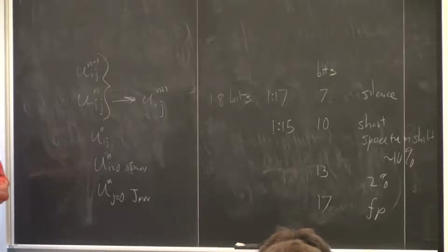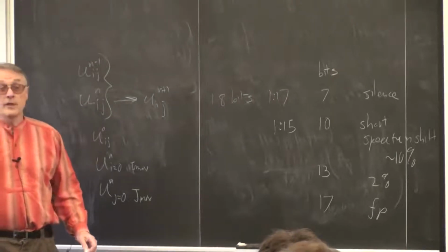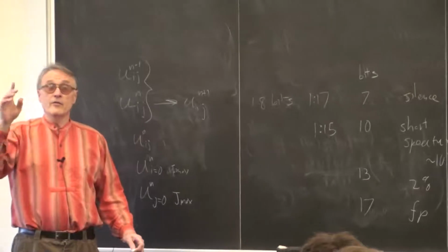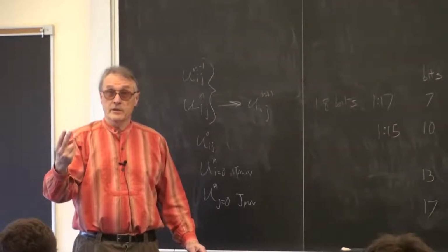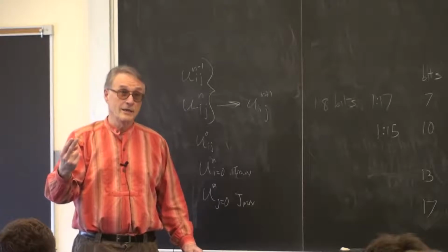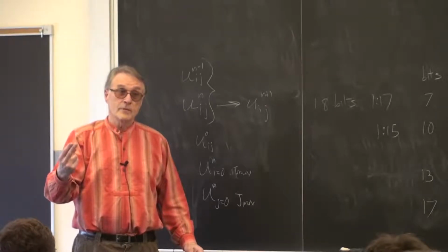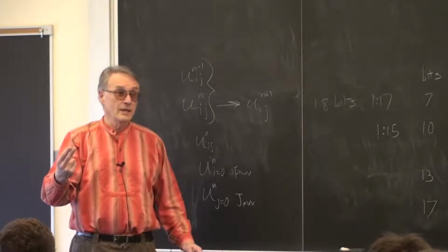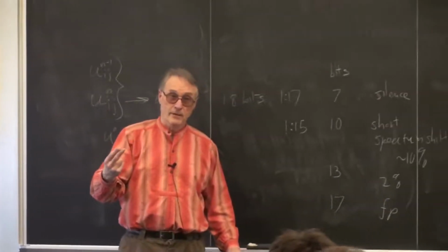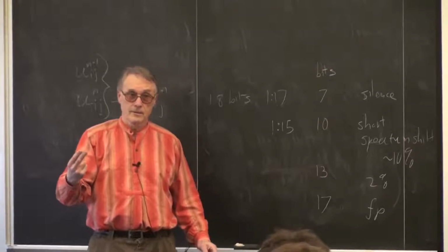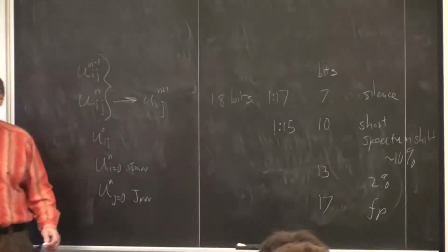And that's what I would recommend. There's a very good reason for using 18 bits, and that is that the native hardware multipliers on this chip are 18 by 18 multipliers. And so they'll do an 18 by 18 full multiply at 350 megahertz. That's pretty darn fast.